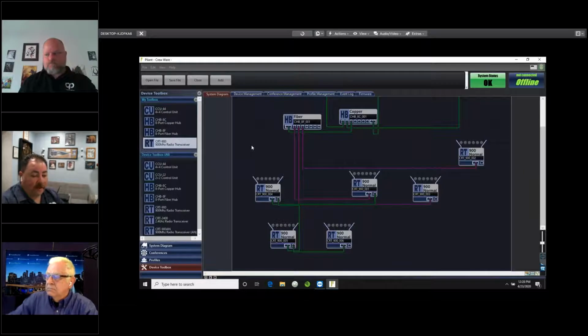The initial way you had to do this was you built your file offline and put your file onto a thumb drive. You would then have to put the thumb drive in the front of the unit while the unit was off, power up the unit, and wait for it to go through its whole cycle to either tell you it had a file or it didn't have a file. If it had a file, you'd have to go to delete system configuration. So you'd tell it to wipe out the file it had. It would then prompt you to power cycle your unit. So you would shut the unit off, turn the unit back on, and let it run through its whole cycle again. So now each time this is a 2 to 3 minute process.